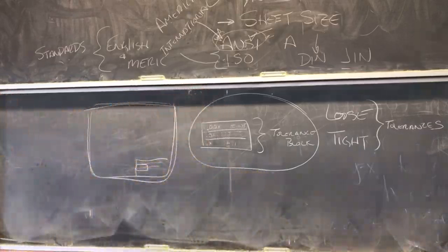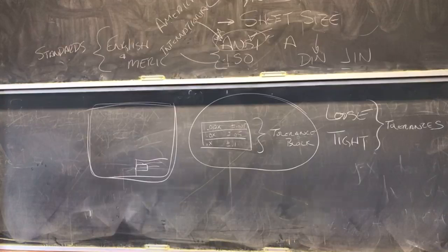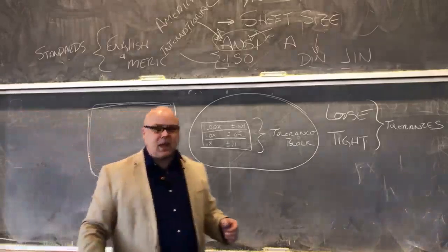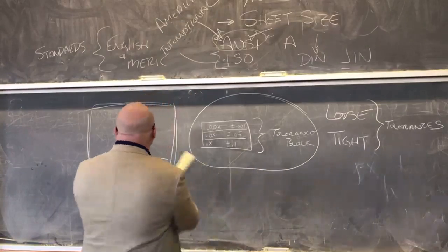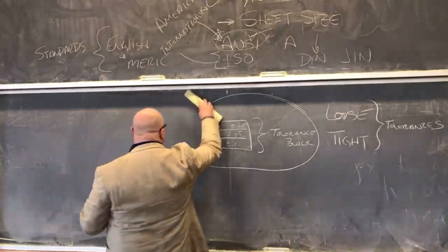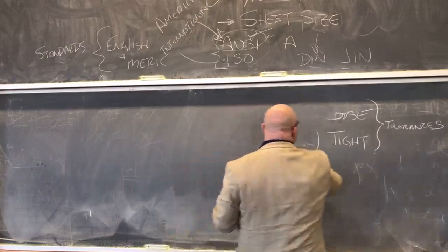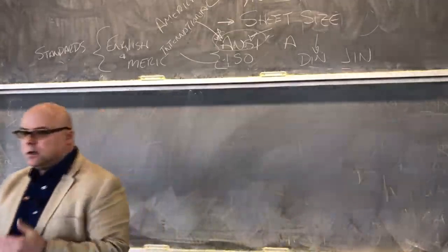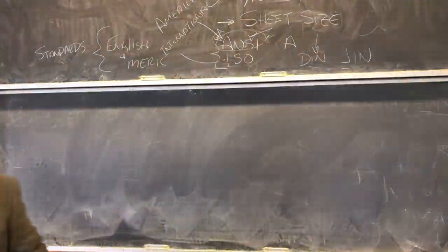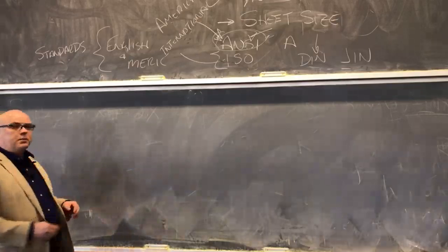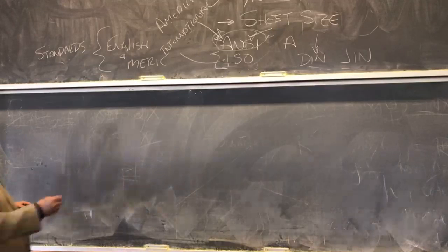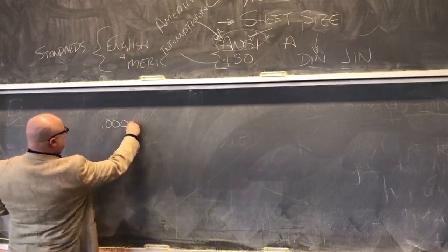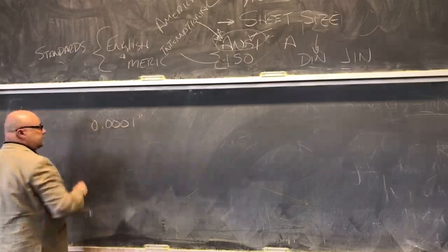Why do we need tolerances? Because not every part can be machined to the exact dimension. It's not because we screw up, right? It's because machines have certain capacities, right? Anybody know what the smallest increment of motion is in a Haas CNC machine? Somebody shout it out if you know. So the smallest programmable increment of measurement in a Haas CNC machine is 0.0001 inches. So a tenth.